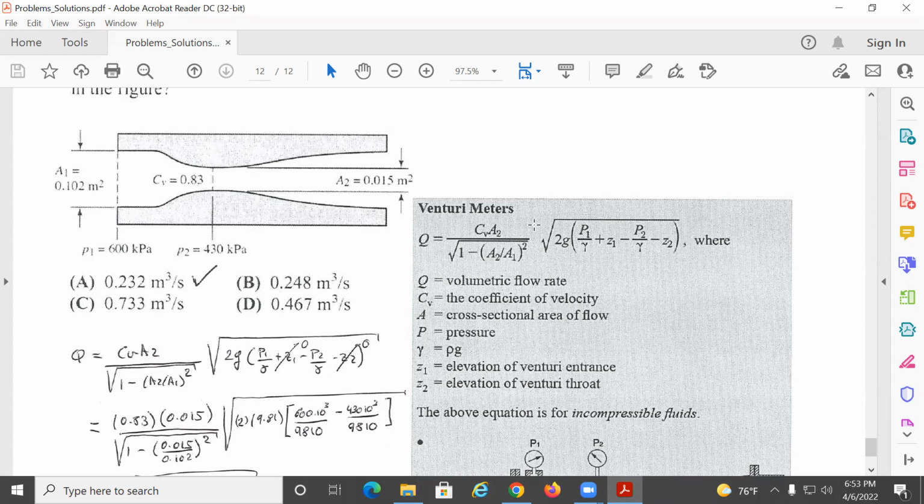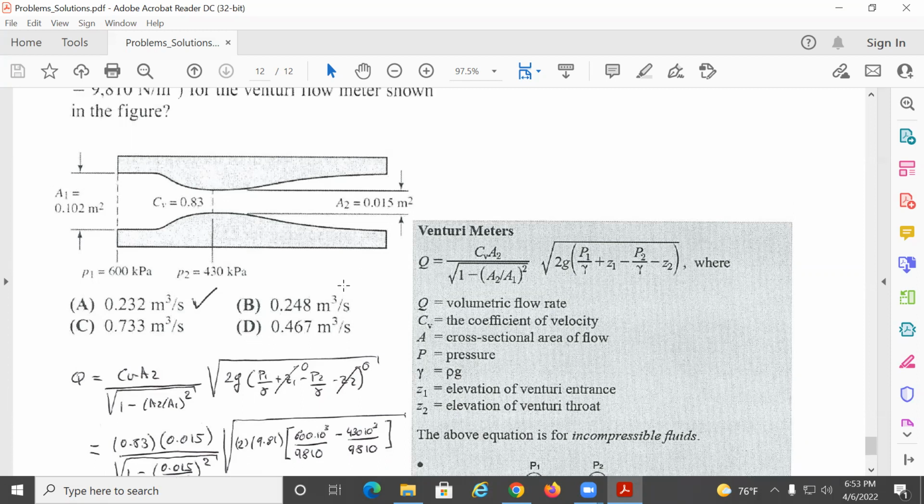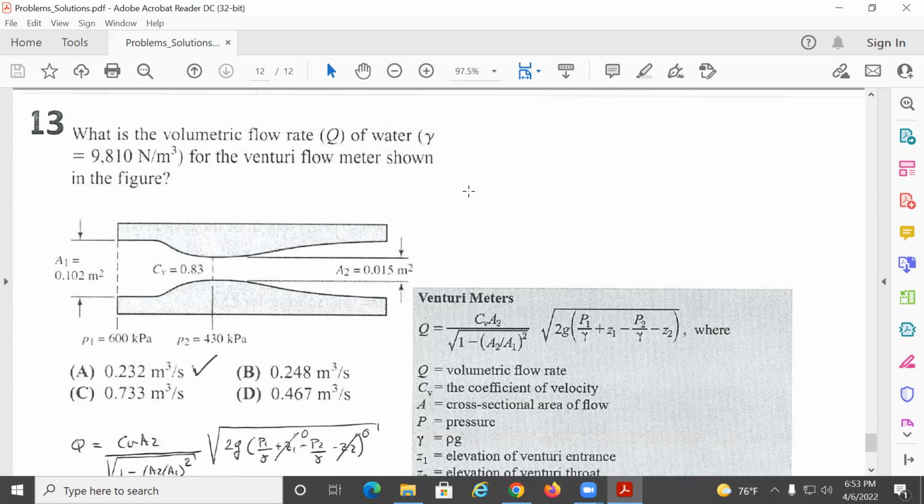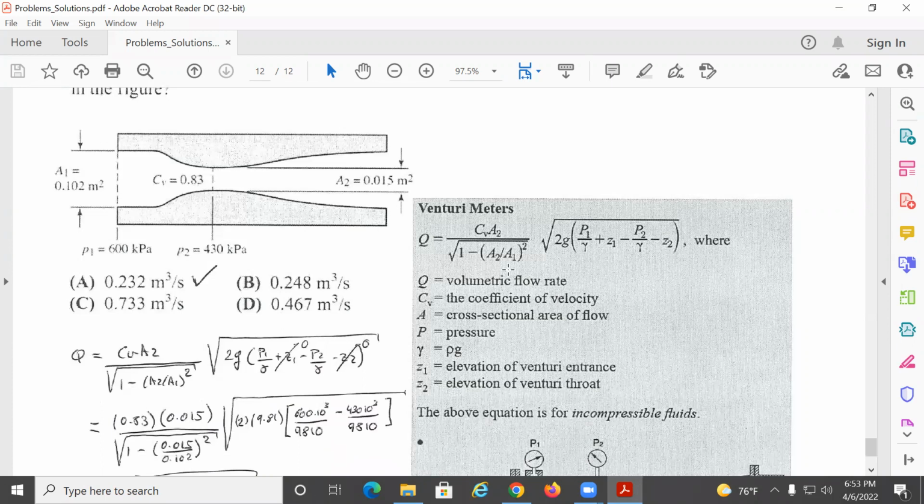Venturi meters are not that much used anymore because right now you have digital sensors. But for example, maybe you have seen in some aircraft, sometimes the aircraft have on their side a little tube that way. It's called a pitot tube, which basically works on the Venturi effect. If you look at the difference in pressure here, and if you calibrate it, it can give you, for example, the density, the velocity, or different aspects of the aircraft that you want to calculate. Again, this would be the Bernoulli effect.